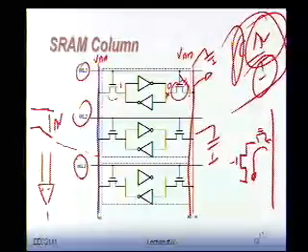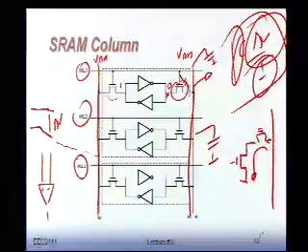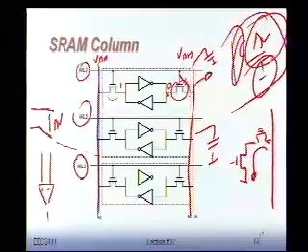And the first thing you observe is that from a read operation perspective, the PMOSes don't do anything. Right? I basically have one thing that sits there. The PMOS kind of keeps it high, but it doesn't provide any current, it just battles leakage a bit. It's the NMOSes that do all the work. Right? If you want to pull the load to 0, I'm going to have this access transistor and this NMOS device pulling the thing down. So the PMOSes are just sitting there for the fun.